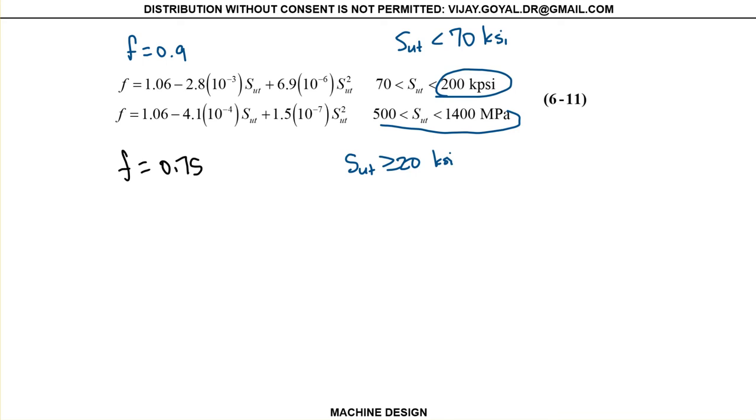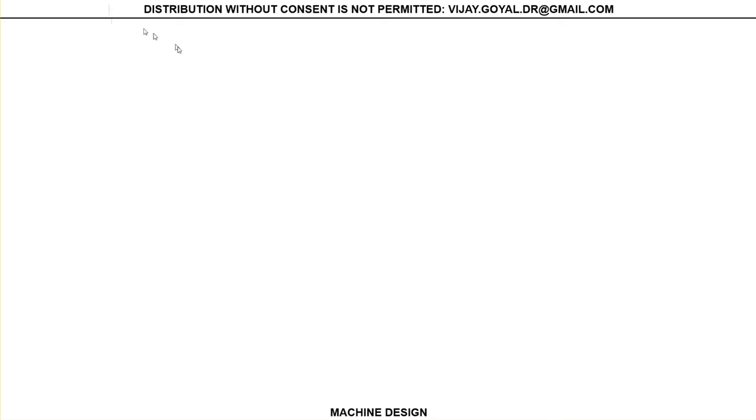So how do I find the endurance limit? The endurance limit is going to equal K infinite. We will talk about this in a minute. That's multiplied by S_E prime. Now, in the case you want to have a stress limit, I call it S_N prime.